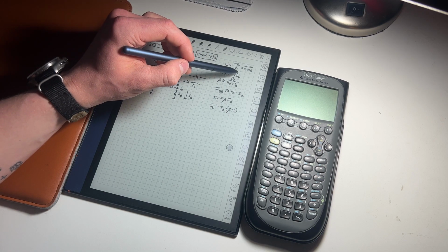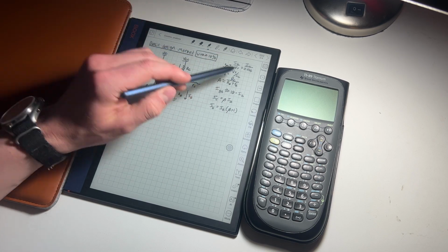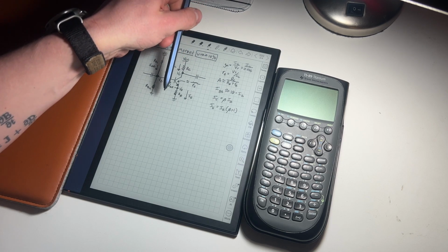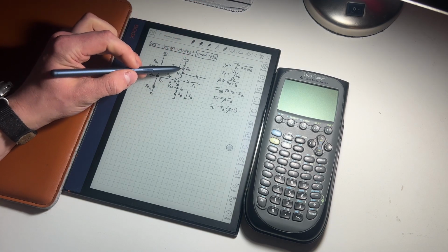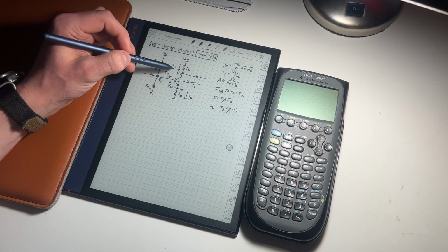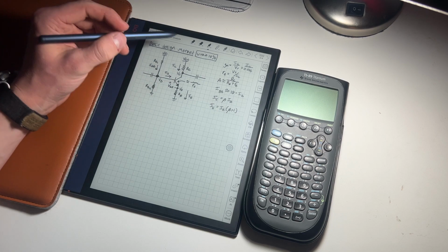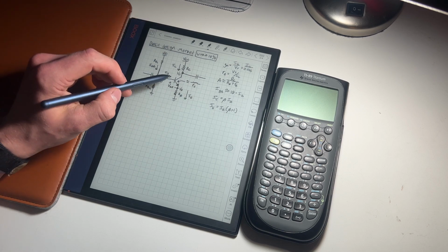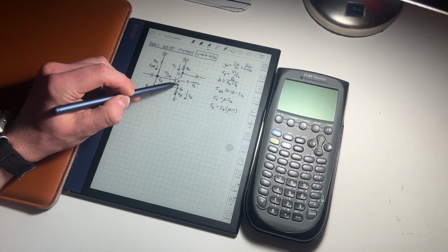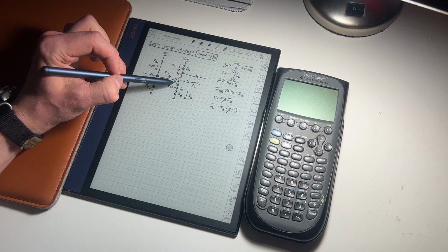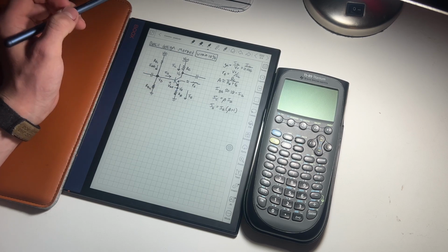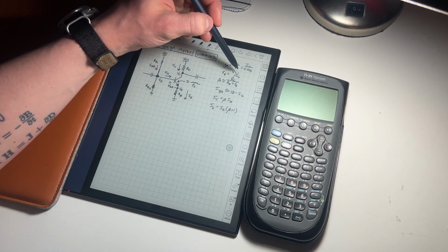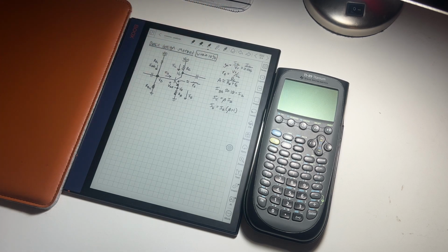Now Vt is being divided by Ic. Ic is just the amount of current that's actually flowing into the collector of the transistor. So by knowing these 2 values, what ends up happening is you have a diode here, and you can approximate that diode across the base emitter junction as a resistor whose resistance is determined by this equation here.